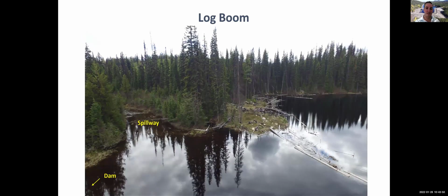So there's the log boom in the spillway. You can still see some debris getting into the spillway. There's some maintenance required. You can see a lot of debris loading in the reservoir. And here's another thing, log booms, do you even need one? We had 1 or 2 people say, I never have any debris. So why have a log boom? If you don't have any debris in your dam and you don't have any potential sources for debris in your dam, you probably don't need a log boom.